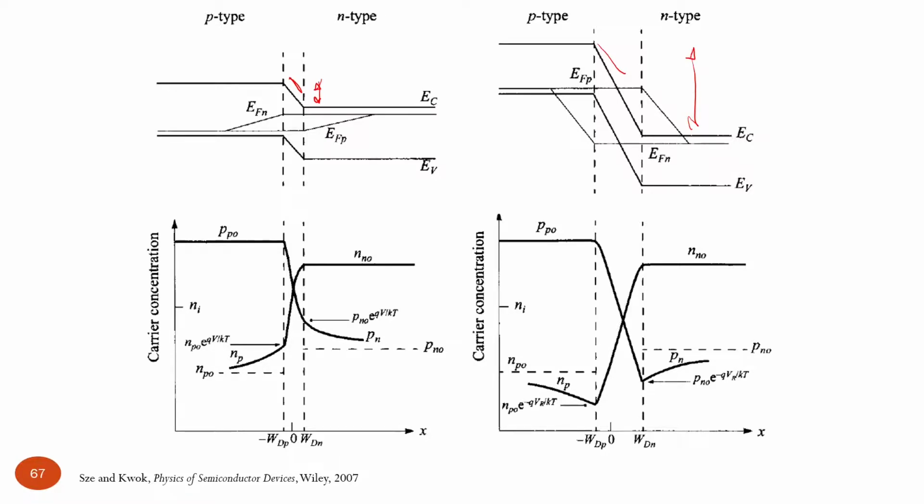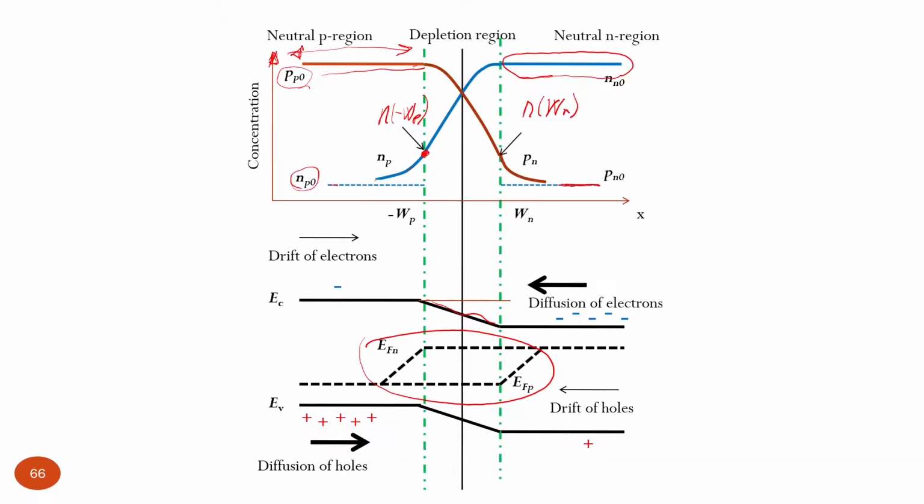So it will not be such a big difference if we consider linear or quadratic distribution. For some cases that could matter, but for understanding the current-voltage characteristic and the key processes when we apply forward or reverse bias, we can easily use this linear distribution of potential.